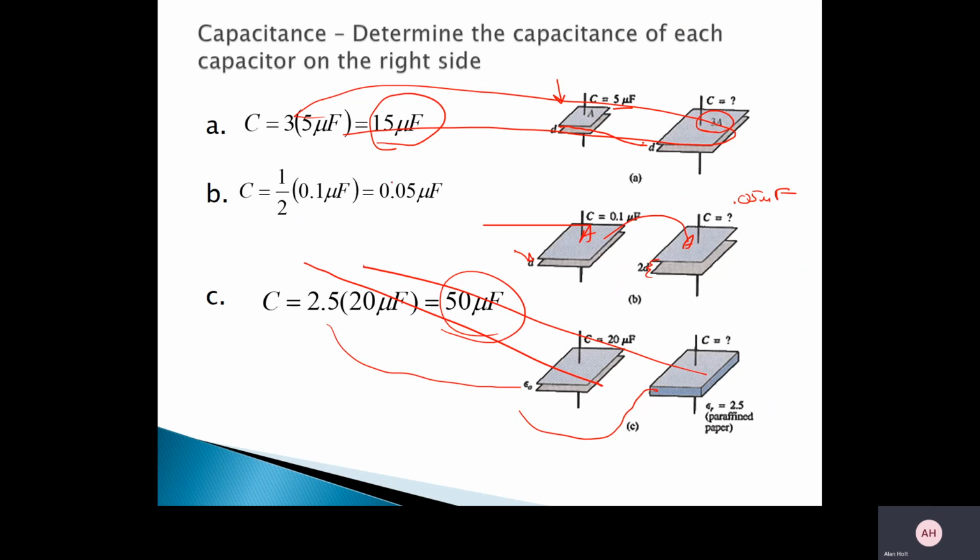Either way, I'm going to have a change in the total capacitance between those windings. So I'm going to have a sensitive instrument, my sweep frequency response analysis, that's going to be able to monitor even extremely small changes in capacitance. And that's what we're going to be looking for.